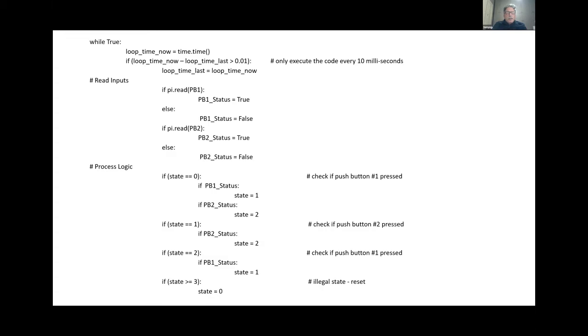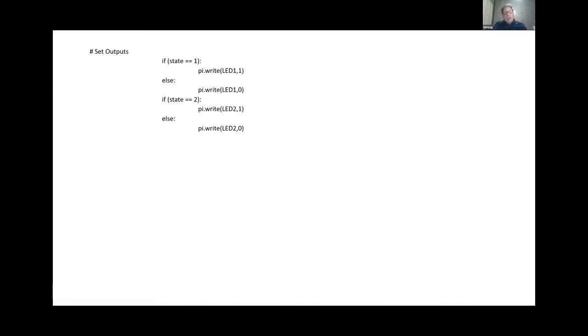So right back at the start up here, where I'm going around this loop, I just put a loop counter in here, and I'll count that up to say 1,000. That will give me a second, count a second. And I will only update the screen when that loop counter gets to 500, and then just reset it, and then that gets to 500 again. And that way I only do certain operations every half a second.